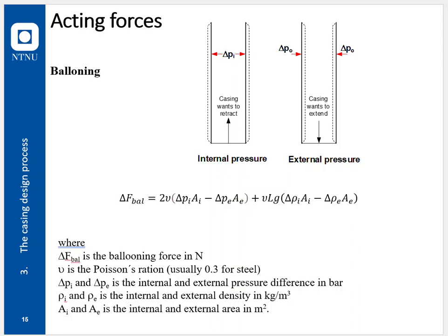Now, what I said about tension added would not be true for a piece of pipe that is fixed in both ends. If you are pressuring in the annulus, then the extension may actually result in a relaxation of the already added tension. It all depends on the situation.